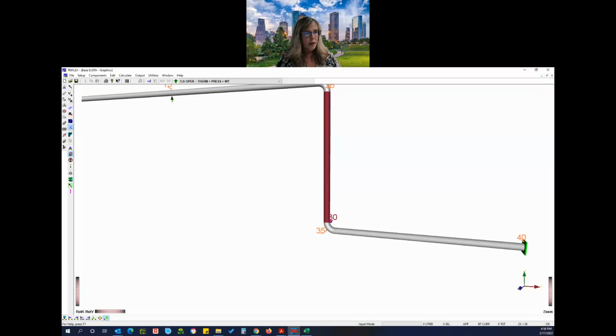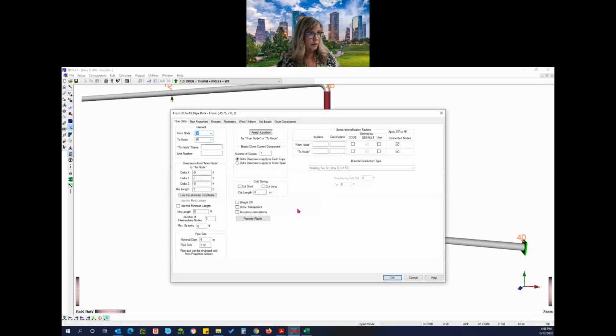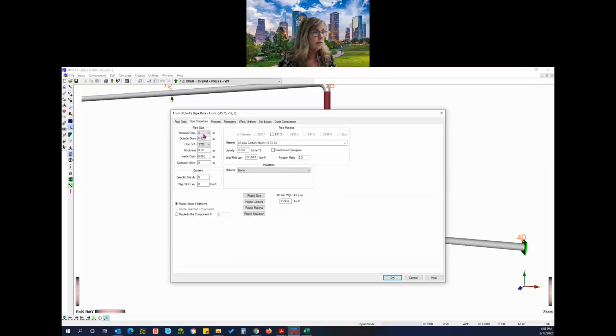It's very simple, as long as you're thinking about your modeling direction and the fact that the pipe is where you're going to attach the base L or dummy leg, either one. You have to attach that. We're going to do a 2.5 foot. So we'll grab the pipe, do a 2.5 foot 4-inch pipe since we've got a 6-inch line.